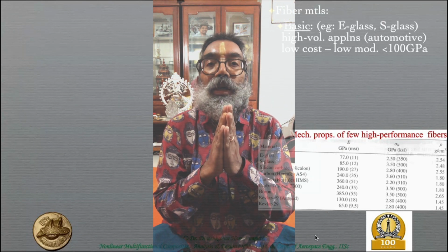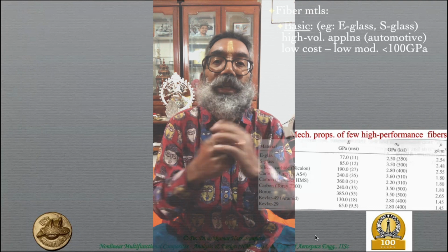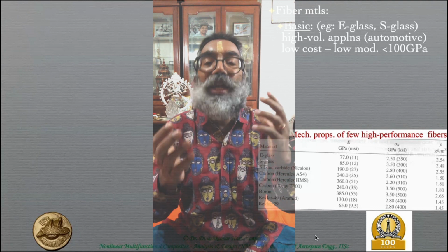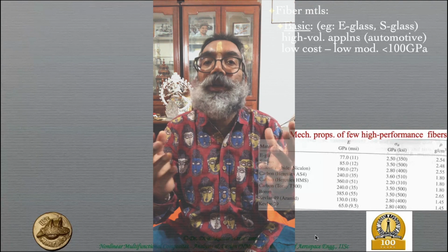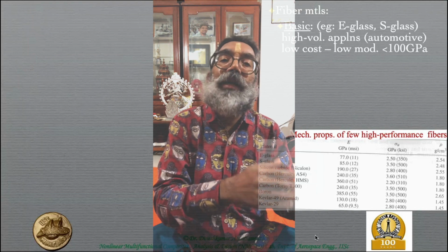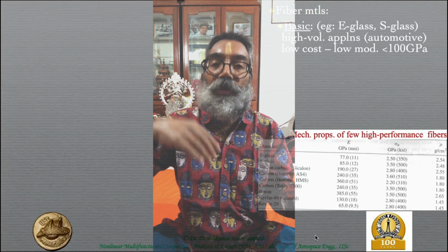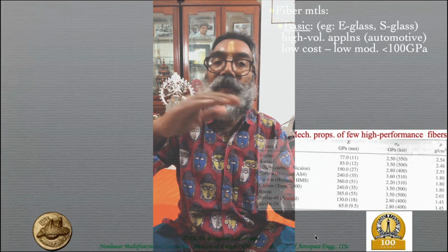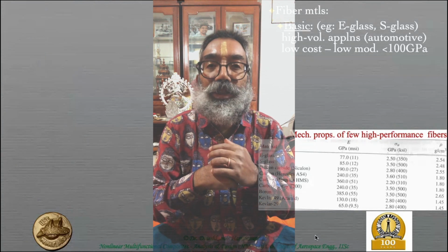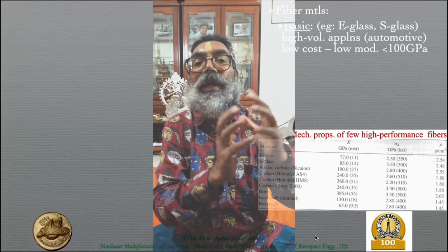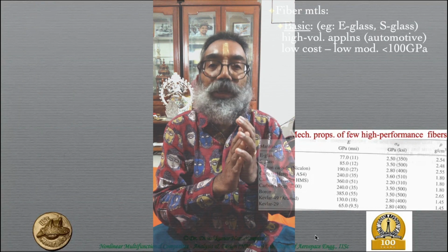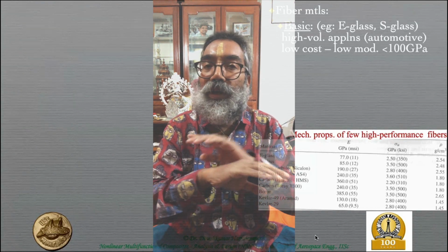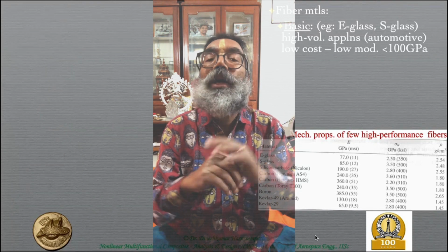material which is imaginary material, fictitious material, that is, which behaves as a structural component. Overall it behaves same as that same component made out of the actual material in terms of fibers, matrices, and each layer having fibers in different directions, etc. So you try to analyze that as an equivalent homogenized material which is anisotropic, having different properties in different directions.